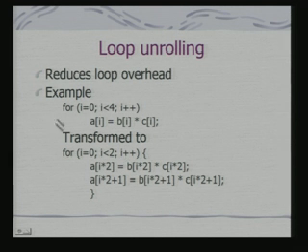So this is the basic idea of loop unrolling: reducing the overhead of loop execution, because loops occupy a very large part of your execution time, since you actually execute code in loops. If you profile, you will find that the time required for different loops varies, and a major part of your execution time is spent in loops. So if we can really optimize the loops, then we can get an advantage in meeting the timing constraints of the design.